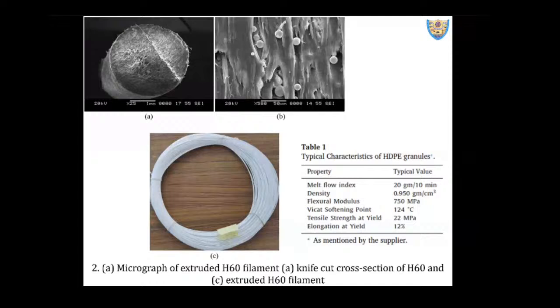we blended them. We initially dried them so that we can remove the moisture. Drying we carried out at 80 degrees C in an oven for 24 hours and then fed to the extruder, which I showed to you. Then for our work, we kept the temperature profile in this extruder at 145, 150, 155 to 145 degrees C from the feed section, wherein the hopper is connected, to the die section, wherein the filament comes out. And again, as I said, the screw speed and the takeoff speed are crucial to maintain the filament diameter. So for our filament, we extrude a diameter of 2.85 millimeters plus minus 0.05 millimeters, because this is what the 3D printer prescribes us to maintain. And for maintaining that, we kept the screw speed at 25 and the takeoff speed at 11.5.